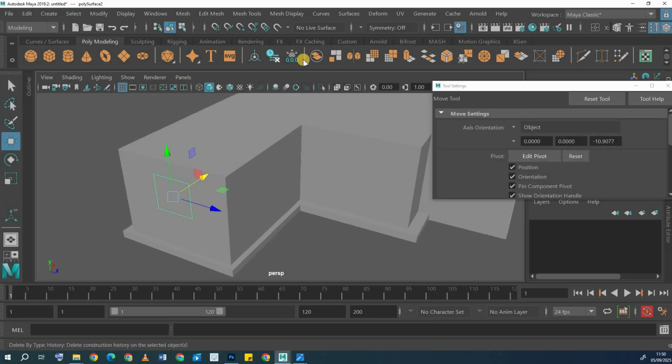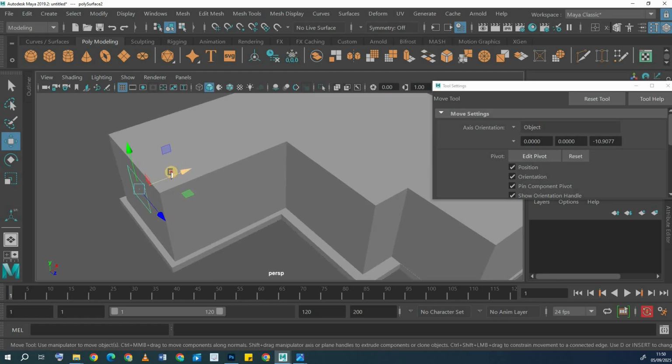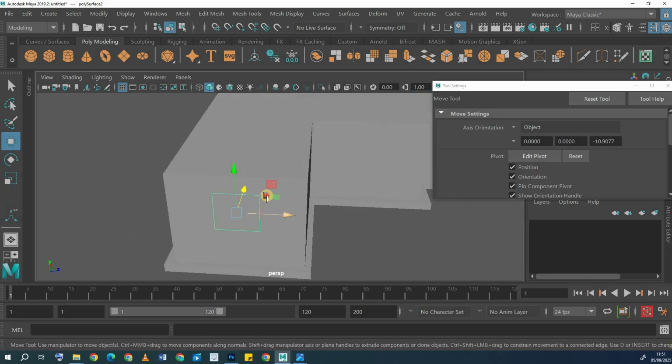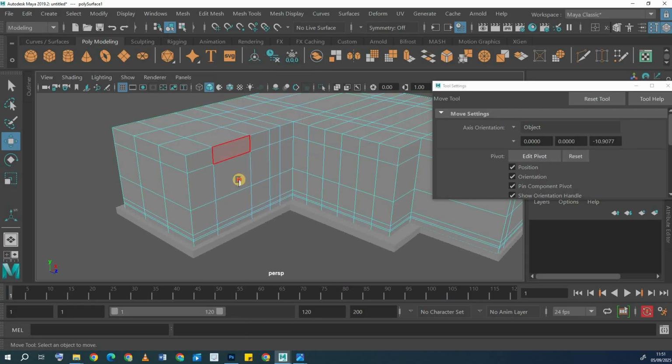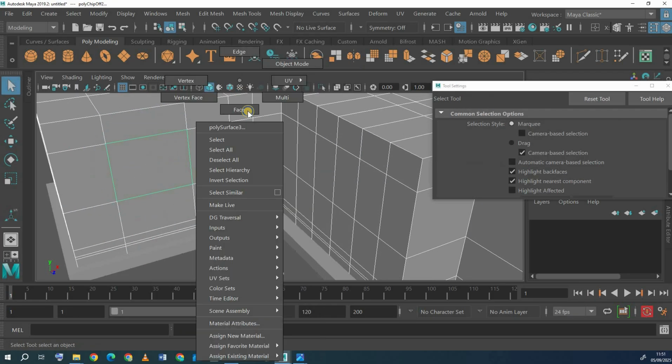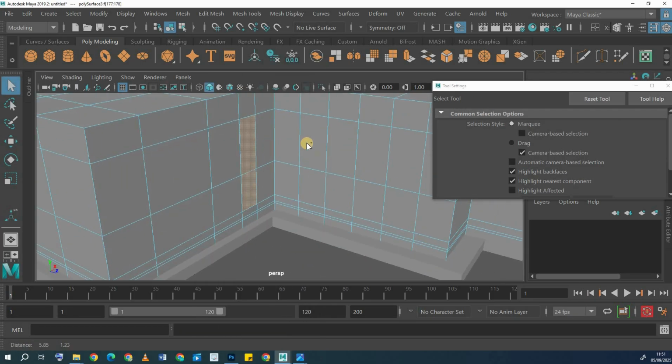The pivot is here. This is the edit history. This is view transformation. We have talked about this. So you see, it just extracts. That's what extracting does. You should have noted that if you have some place to note. So it just removes that panel from the main shape. Very useful tool in this case. So Ctrl Z, I'll put back, but it leaves it in place. Then I'll come back and extract my other window here. Then I'll come back here and extract my other window here. So I can extract them actually at once. I know where all of them are.